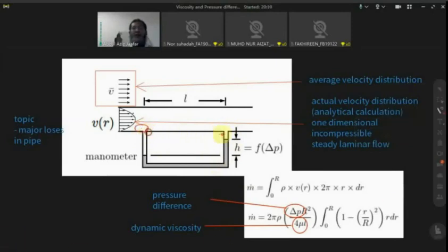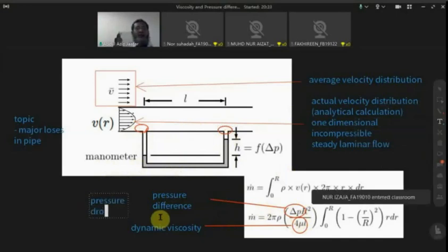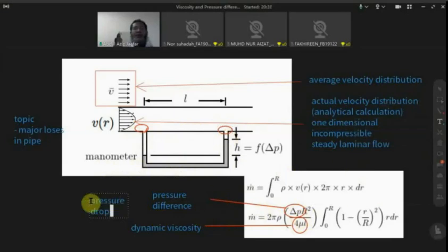So I just show you the location of the orifice. As you can see, for this schematic diagram, we are measuring a flow of gas in the gas phase, because the manometer fluid is much more dense than the gas. So we have to place it at the bottom of the pipe.